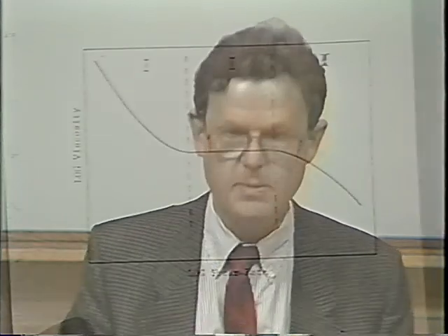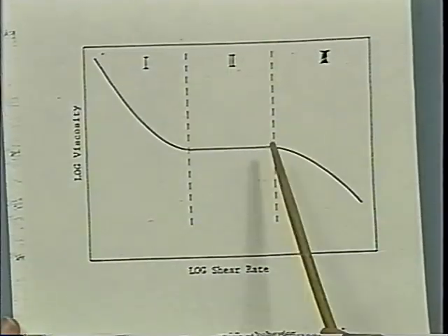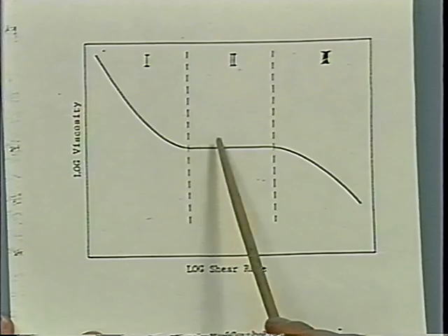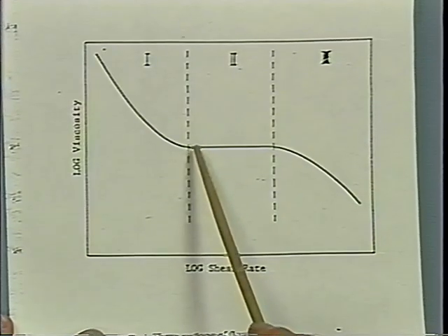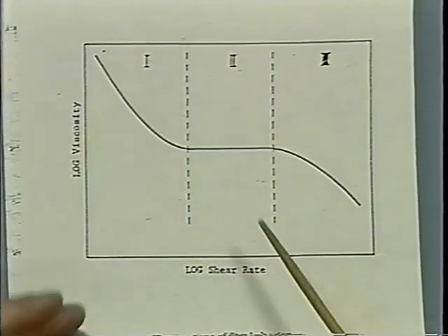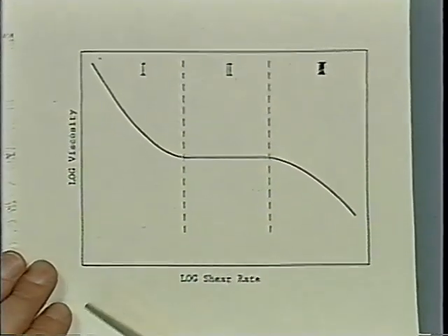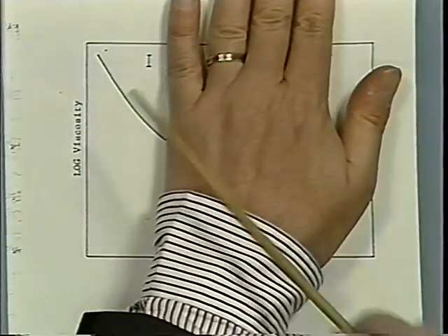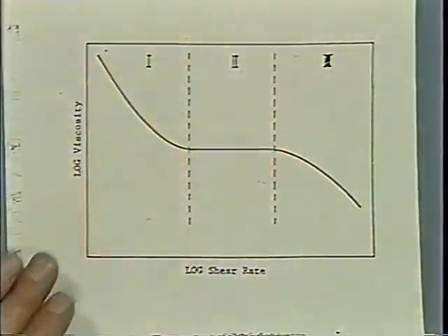In the literature, there were many proposals of this type of viscosity curve. Especially materials with structure were said not to have only a zero shear viscosity, but that at very low rates they would have an upturn in the viscosity curve. And the same model has been proposed for liquid crystal polymers. It's not clear whether we are operating in this upper region or in this lower region. So for the thermotropic systems, it's really not completely settled whether this viscosity function even applies.